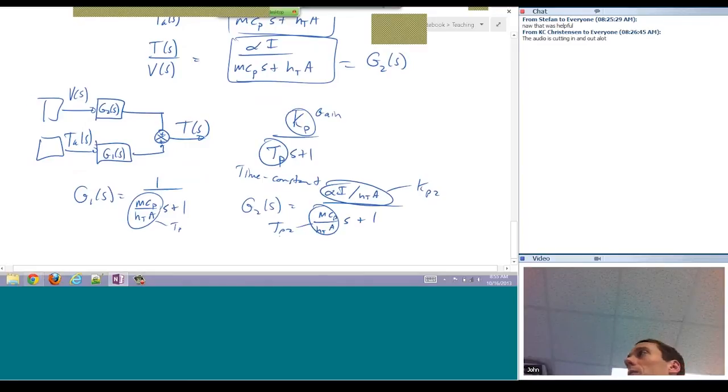If you have an estimate of mass, say 1 gram or something like that, you can plug that in. And if you know a heat capacity, well, with the transistor you've got multiple metals and other things going on, so just make an assumption, like this is steel, or whatever transistors are. You can make an approximation there, just to try to pick out values, because what you want is a heat transfer coefficient. You can isolate that. Your area there is going to be an issue, so just go ahead and throw in best guesses for those numbers. You're not going to use that, but you can try to pick out different parameters that way.